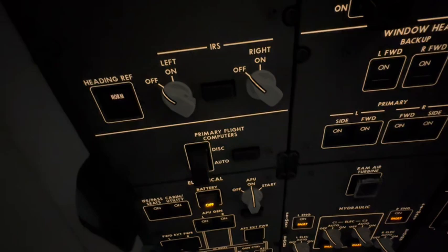Up next, the primary flight computer toggle switch. You got 2 options here. Automatic and disconnect. In automatic, the airplane will be in its natural state. The computers will basically take care of everything. You hit that disconnect, you're gonna go into direct mode. Remember, there's 3 modes: normal, secondary, and direct. Direct mode, you're flying that airplane with no augmentation. Airplane is no longer helping you. You have direct control. Above that, you have your IRS, your inertial reference system.